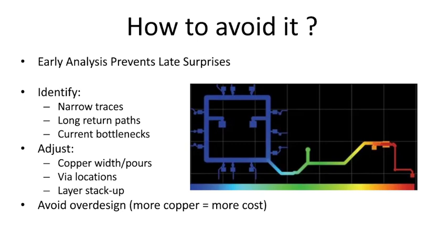Whenever we are checking for a DC drop analysis, it's very important to identify what is causing this issue. So in this case, let us say that we have a VRM. VRM is voltage regulator module. Usually that component is called PMIC. The PMIC components generate the DC supply to these ICs.